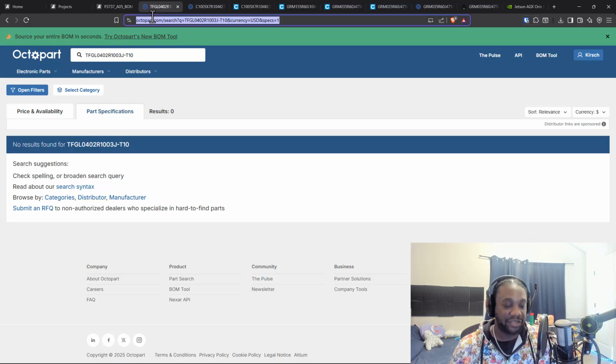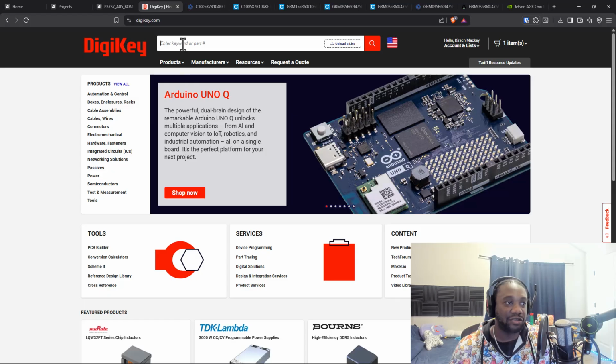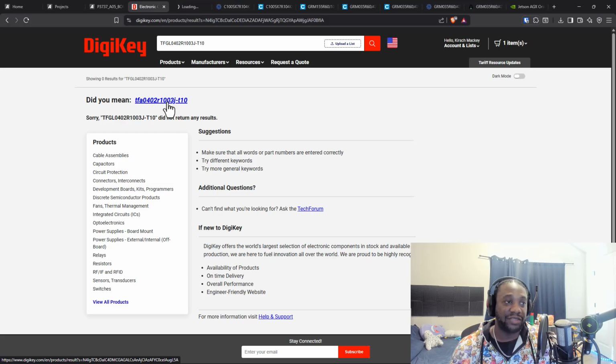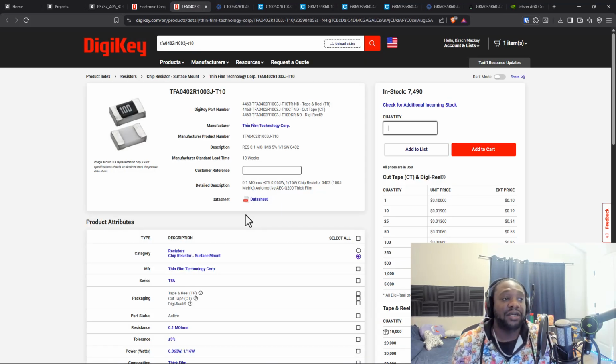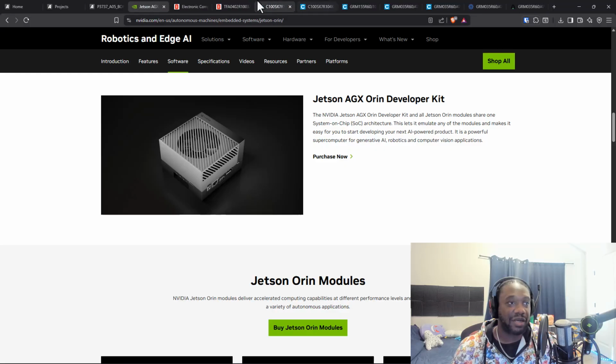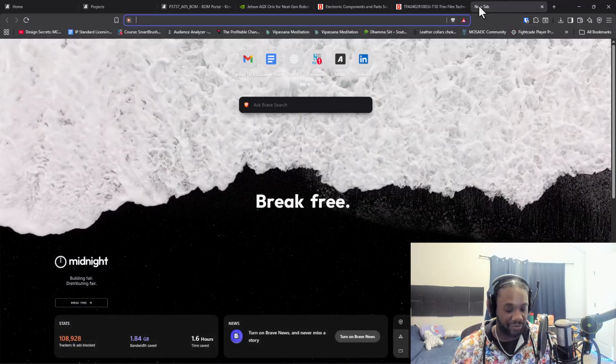See if it comes up with any suggestions. Let's go to DigiKey. DigiKey is really good at recommending suggestions as well. So let's see if there's anything here. And it's asking, did you mean this? Let's see, TFA 0402 R103JT10. That's a very close number. It could be that the manufacturer literally just changed it. To verify, let's move this over and close my tabs to the right. Look for this part number.